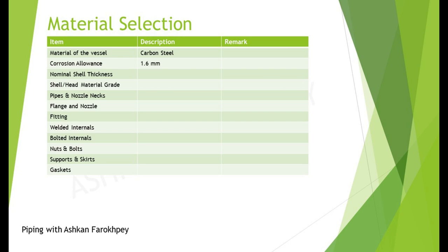Typically, we give the corrosion allowance to the mechanical group, and they use it in their thickness calculation. We did it in our project, and the thickness that came out from the mechanical department was 11 mm, considering pressure, temperature, occasional cases, corrosion and construction allowances, etc. In other words, our nominal thickness is 11 mm. As we now are aware that carbon steel with 11 mm of thickness is our choice, the next step is specifying the exact UNS or ASTM grade of all components in our vessel.